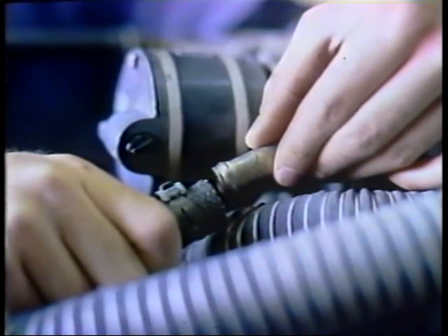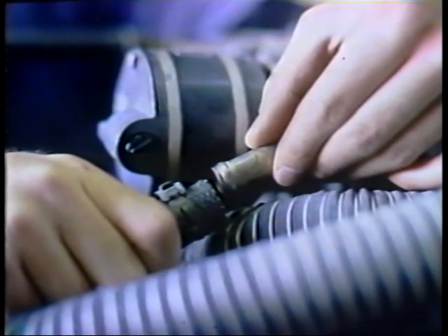After the pump is installed, connect the hoses, being certain that they are perfectly clean inside, free from any oil, solvent, or foreign debris. Be sure that the hose laminations are not separating, as sections or pieces of the hose are instant death for the pump.